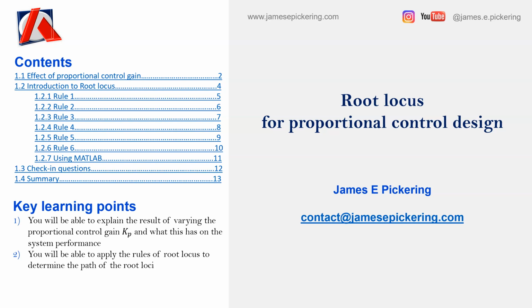I'll then introduce you to the rules of root locus. The rules of root locus are going to show us the path of the poles on the z-plane as we increase the proportional control gain from open loop pole positions, where kp equals 0, all the way up to infinity. I'll run you through the 6 most basic rules that you need to be able to draw the path of the root loci, and then I'll show you using Matlab.